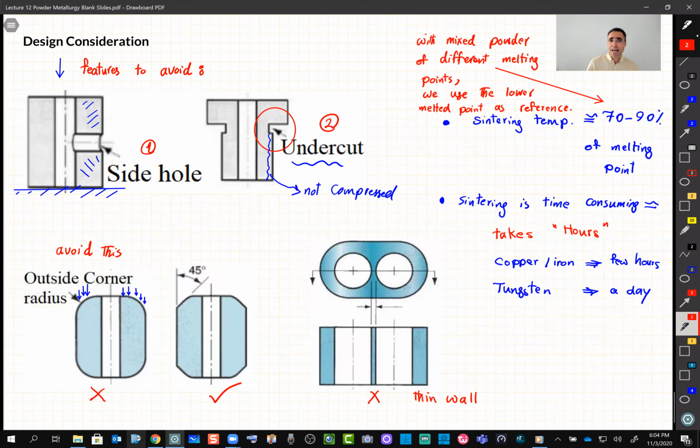Again, it depends on the application, but in most cases the surface finish is almost at the final stage, unless we want something, let's say those rings for pistons that I showed you, which need a very smooth surface. Then the secondary process is not going to be a lot of machining, maybe just a simple sanding, and then it will be done. But the surface finish is usually good.